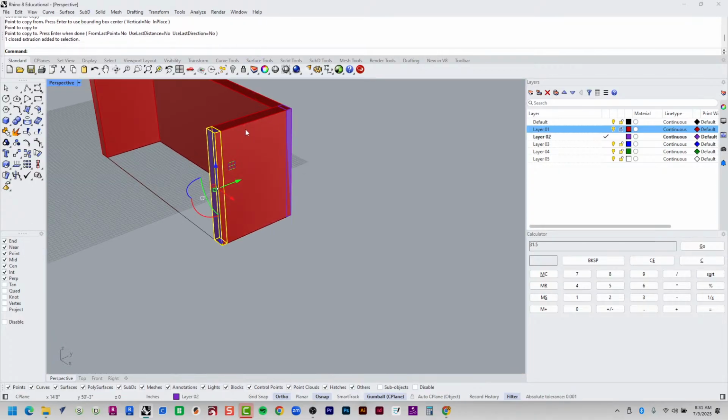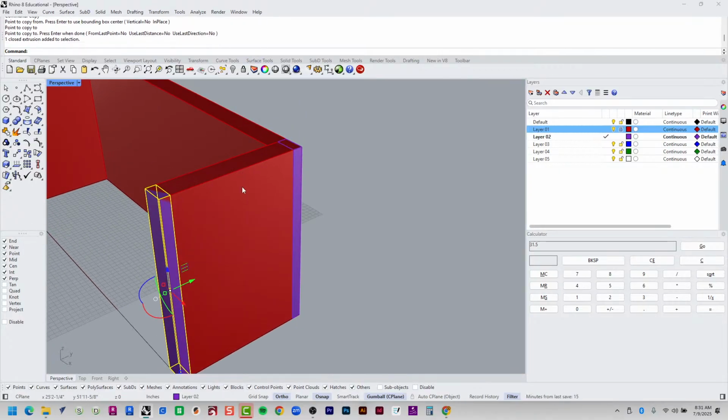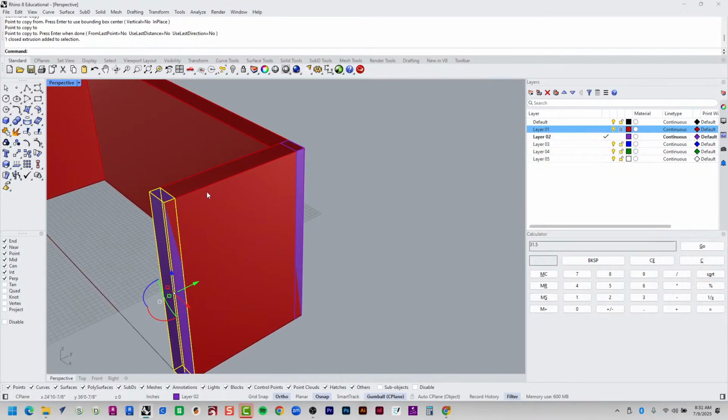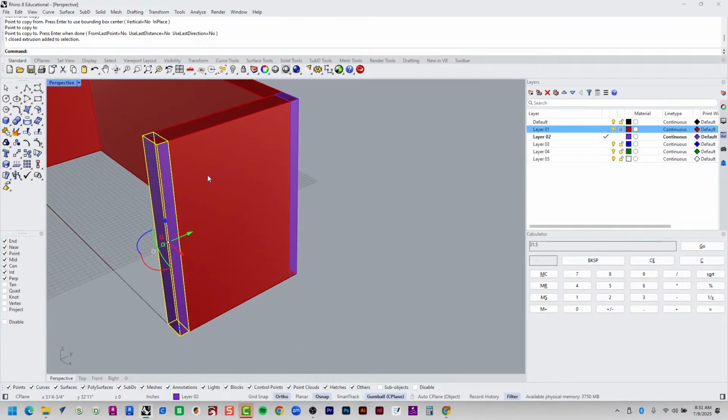Now let's worry about doing the middle stud. I might need a middle stud. I might not. It's 2 feet deep here, so I actually don't need one. You should put a stud every 2 feet on center. Okay? If you have a gap between your studs that's over 2 feet, that's a little too much. So 2 feet on center is standard with 20 gauge light gauge steel.